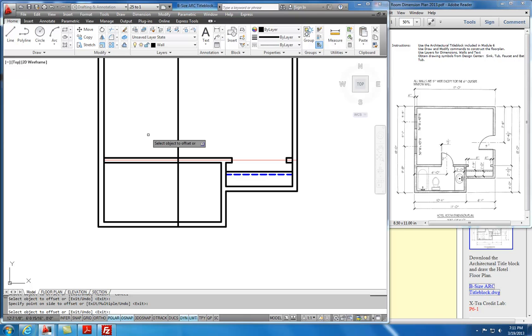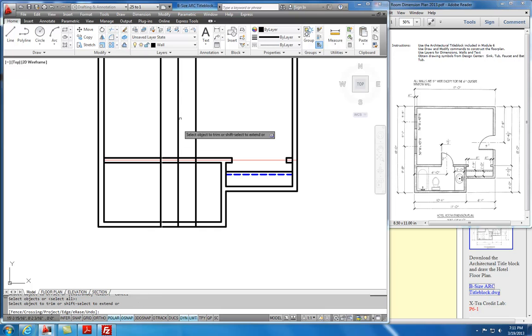And actually I think it's 2 feet 6, but from an example of making this an accessible door for somebody in a wheelchair, I'm going to update this to be 3 feet. And so I'm going to offset this 1.5 feet to each side. So we'll offset this 1 foot 6 inches to this side and to this side. And then we will trim, enter, and we'll remove this, this, this, this.